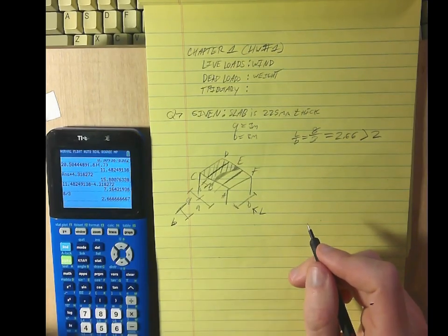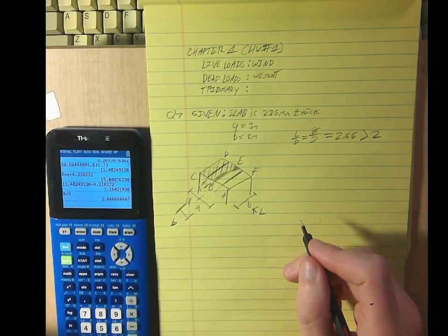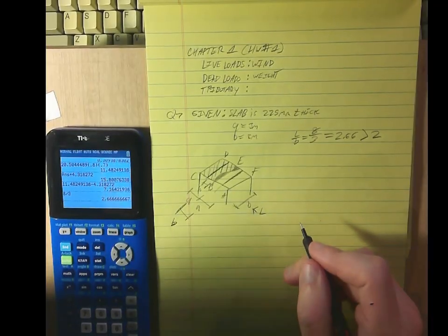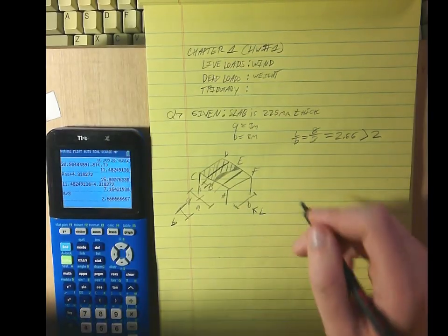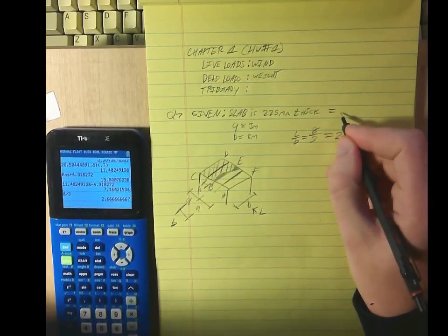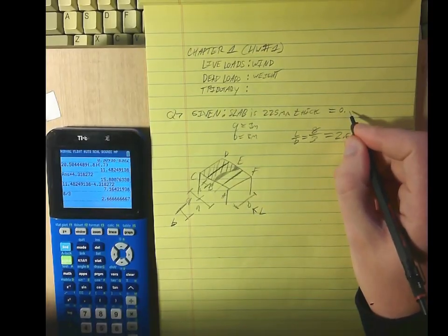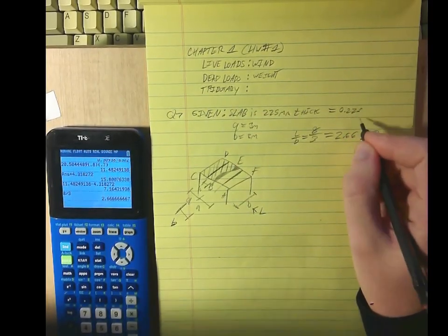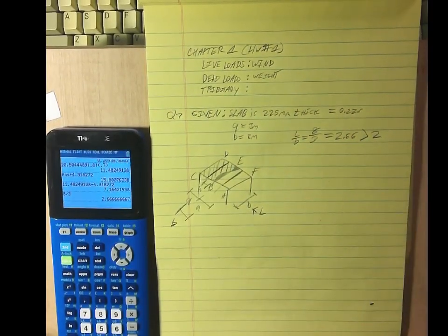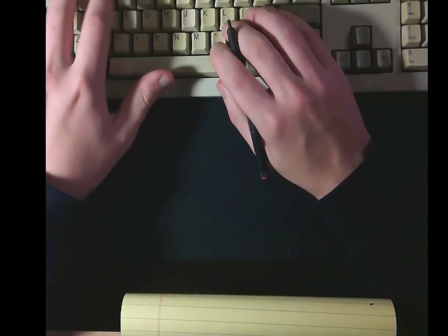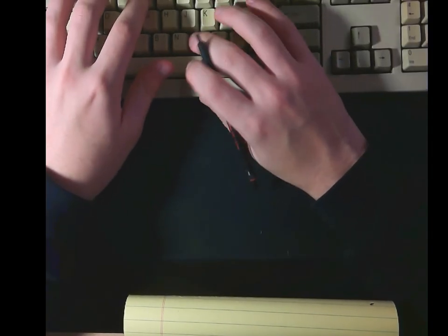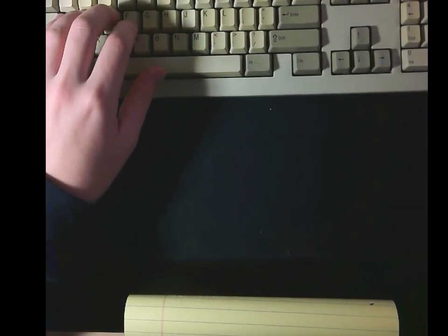Now from here, what's the weight acting upon this? We know the thickness of the slab. Are we told that the slab is concrete? If we're told it's stone concrete, so this is going to be 0.225 in meters, 225 millimeters to meters. Yeah, 0.225.